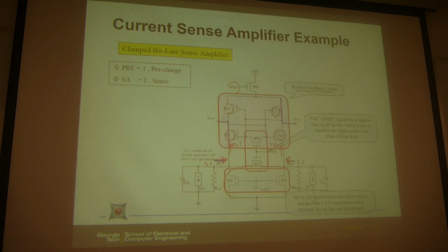Because sense amp enable essentially will connect your latch either to the VDD or ground. So before you turn on the sense amp enable, it's okay because the circuit is floating. So those 2 points of the latch will be at equal potential. But once you develop the difference of those 2 nodes, then you turn on the sense amp enable. Then you have a path to the VDD or ground. Then this latch will flip.